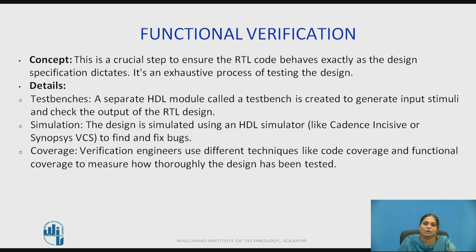The test bench plays a very important role in functional verification and is written using Verilog coding techniques. The design is simulated using an HDL simulator like Cadence Incisive or Synopsys VCS to find and fix bugs. Verification engineers use techniques like code coverage and functional coverage to measure how thoroughly the design has been tested.